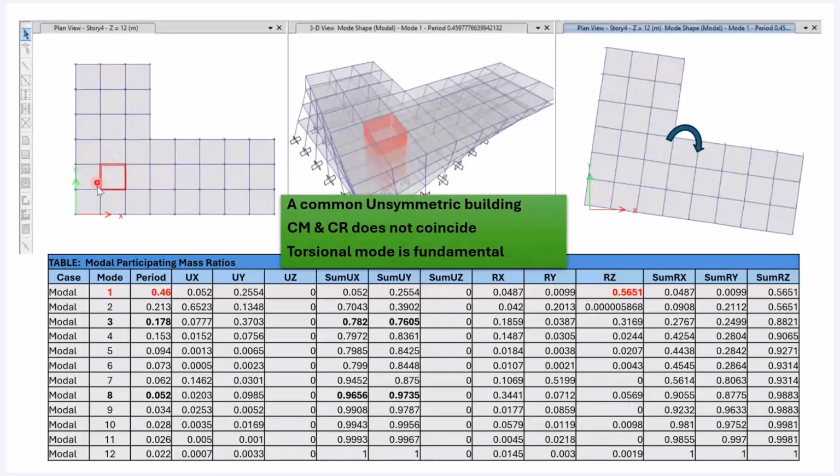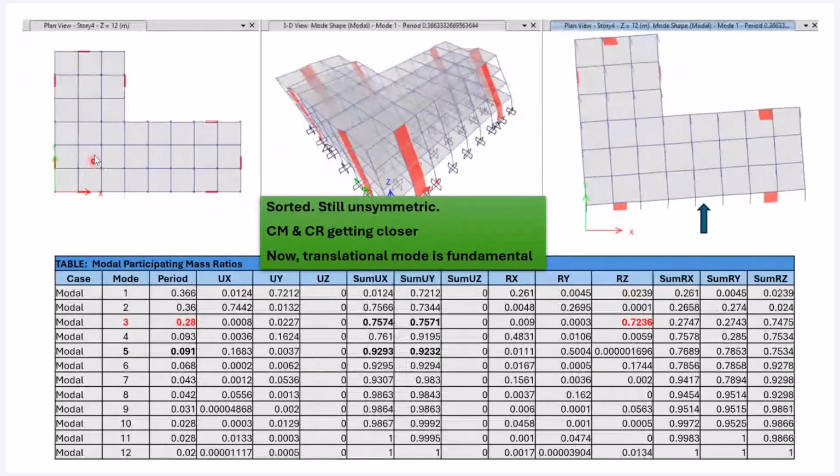You can still use the core wall, and then other distributed lateral load resisting system. I removed the entire core system there and then distributed the same amount just to keep the quantity of shear walls the same and to show now the torsional mode has come in the third, and you can see.